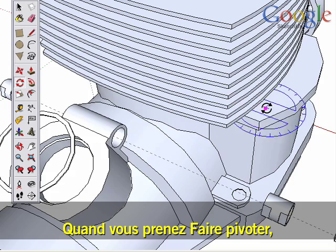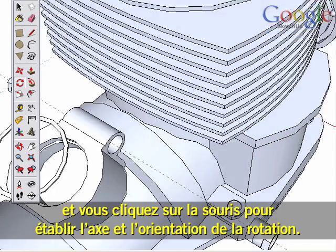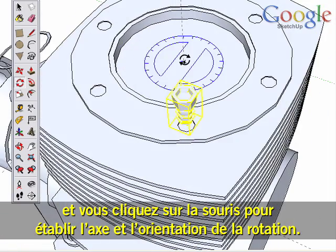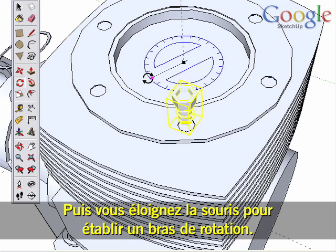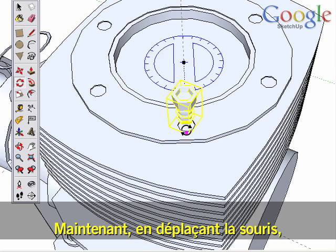When you pick the Rotate tool, the icon orients itself to any surface you hover over, and you click your mouse button once to set the rotation center and orientation. Then you move your mouse away to establish a rotation arm or base. Click again to set this base.